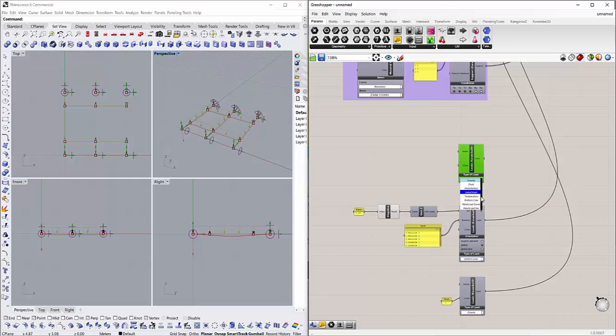So uniform line load, and this will be acting along y direction as the glass load. The load which will be transferred by the glass is going to be added here. So I'll enter the transoms on which these loads will be acting.